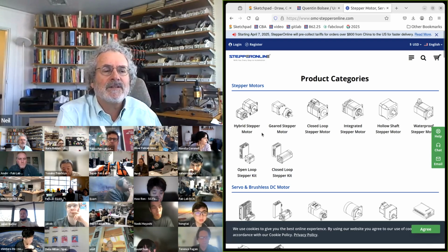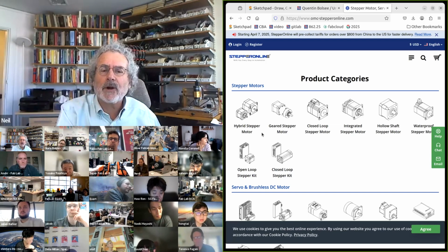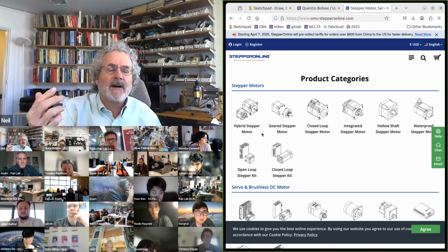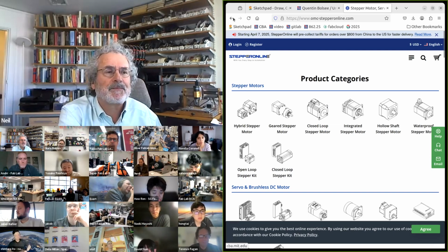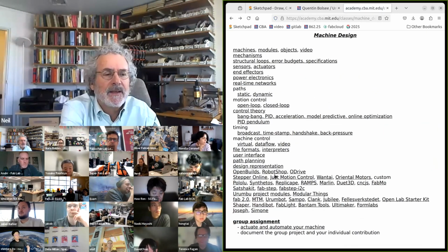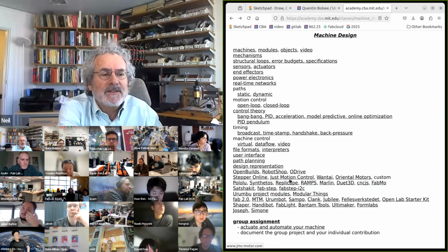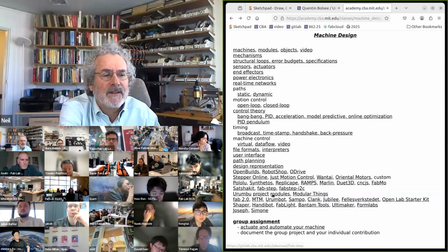And then you can decide, do you want a stepper motor, a servo motor? Remember, motors have a torque where they're most efficient. A geared motor has the reduction built right into it. So those are much more convenient to buy now. Then these are all standard solutions for controlling the motor. So Pololu is a vendor that has lots of motor controllers.